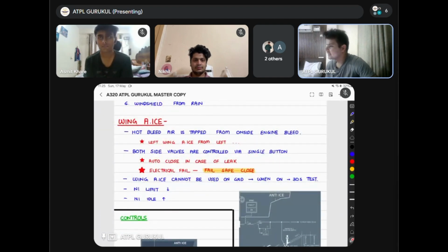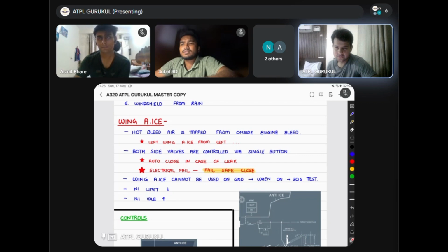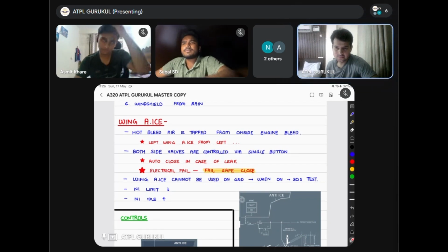Now my first question to you is, can you use wing anti-ice with APU bleed? Where is this point written? That you cannot use wing anti-ice with APU bleed. Ashmit? Pneumatics. Pneumatics? I don't think so. APU limitations. Okay, it's there in APU limitations. Okay, great.